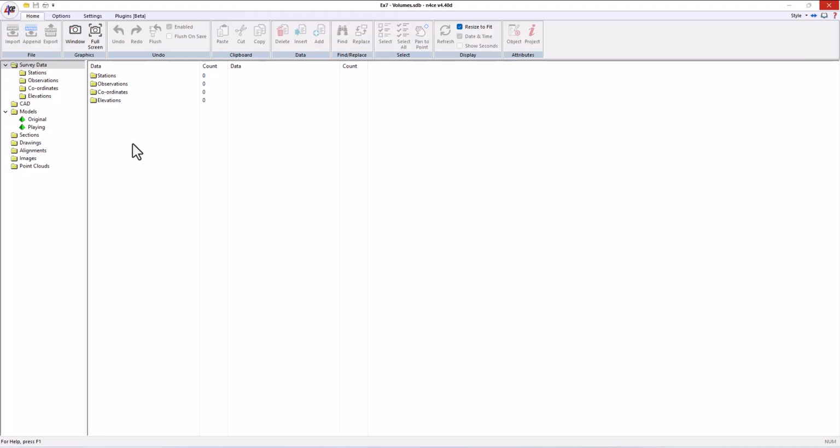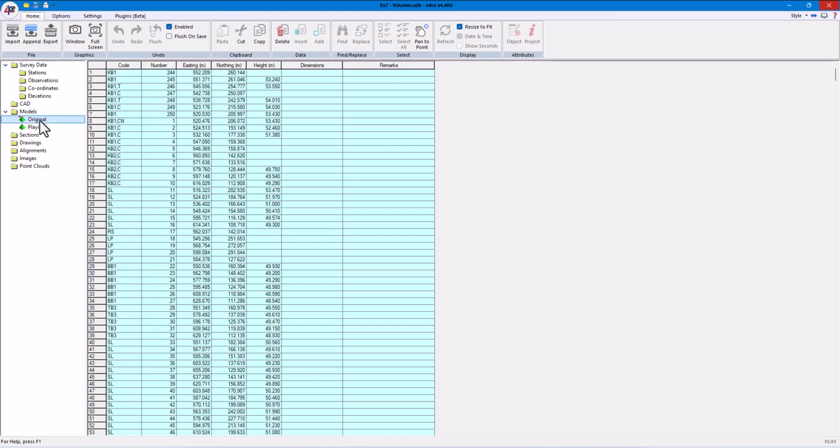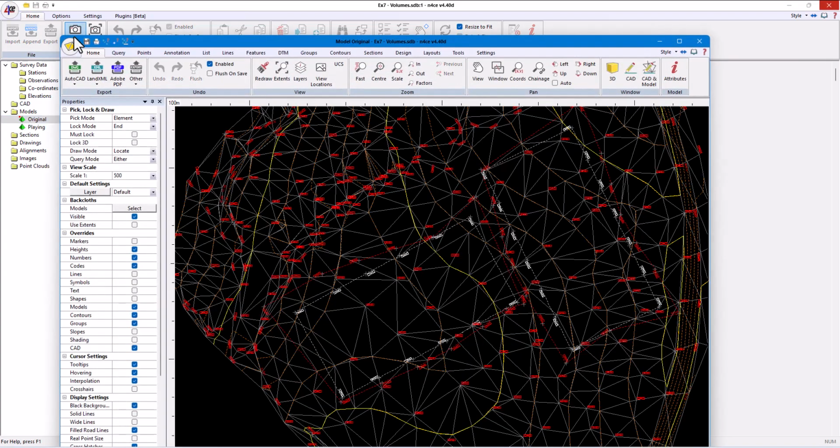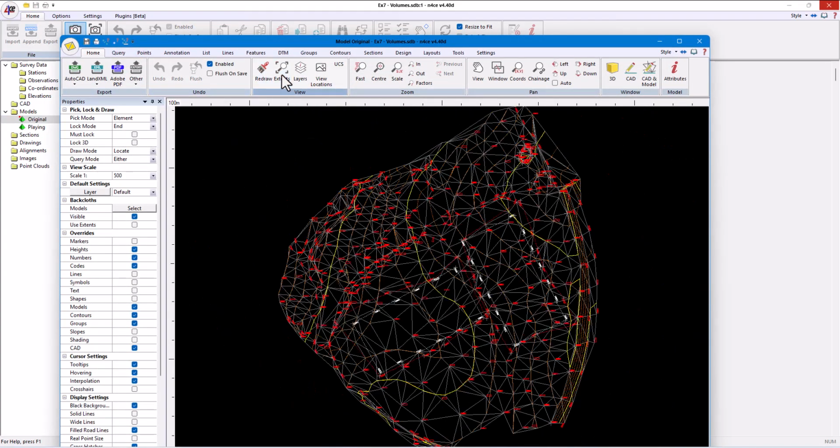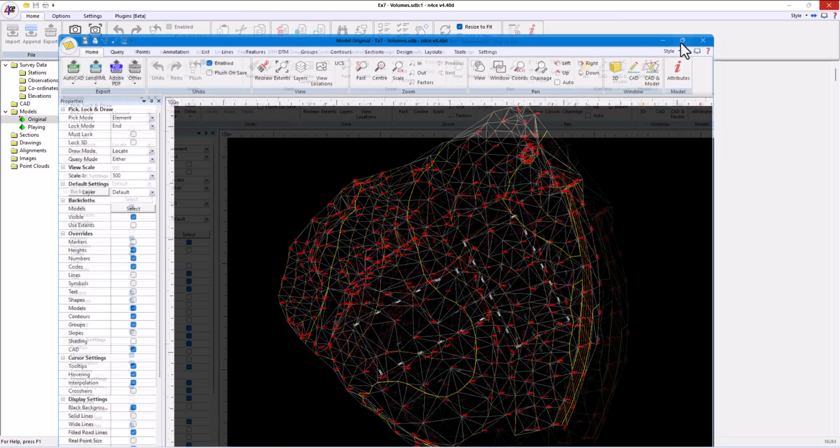One is an original ground model, or OGL. The other is a simple layout of 2 football pitches with basic batters calculated in another package. Our task is to improve on the design, as it currently does not balance. By this we mean that the volume of material excavated or cut is not equal at all to the volume of fill that must go back in.